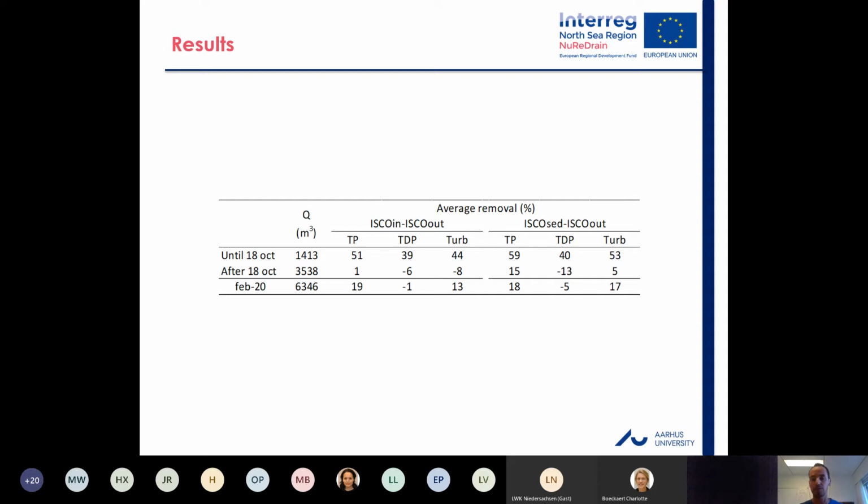It dropped because the sediments were not taken by the sediment filter and partially clogged the reactive filter. This reduced the absorption capacity of the filter itself.